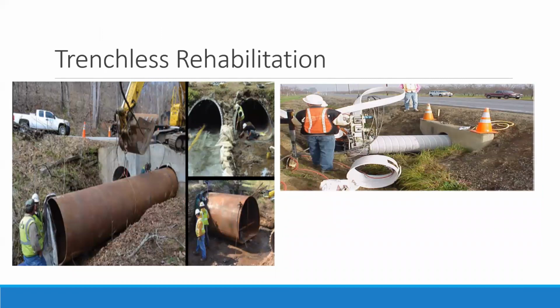So what is trenchless rehabilitation? Well, trenchless rehabilitation of culvert pipes takes maximum advantage of the remaining usable structure so that the pipe is returned to its initial condition or better. Trenchless rehabilitation methods have less impact on the public since they can be done inside of the host pipe and without the need to close down any of the roadway or traveling surface.